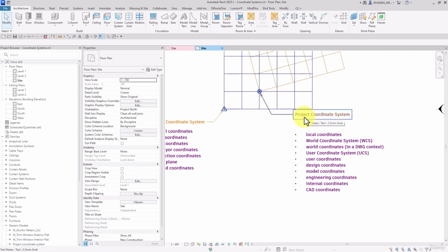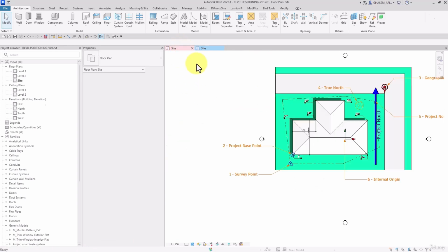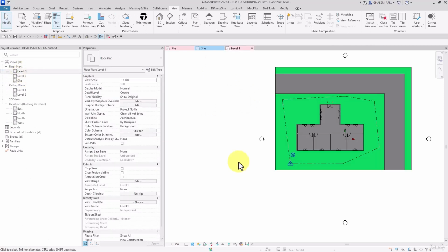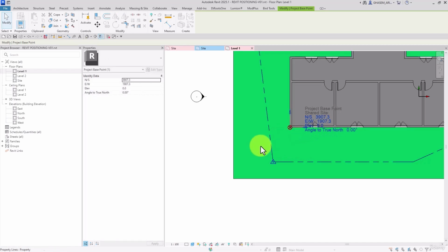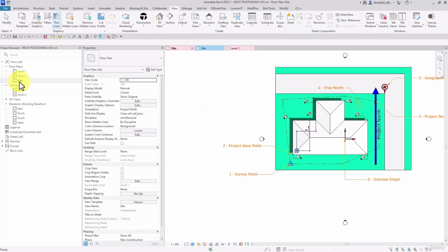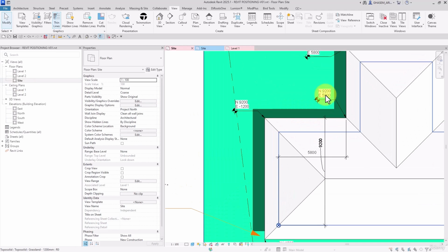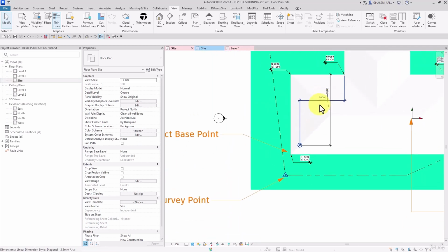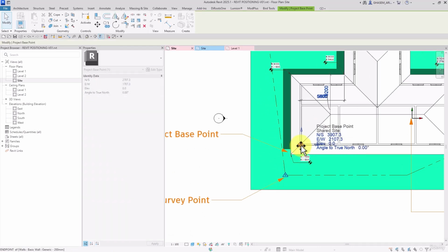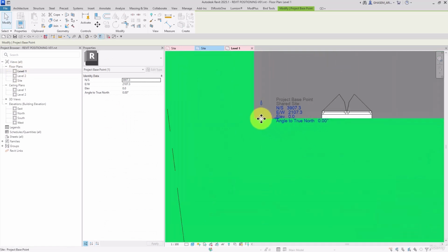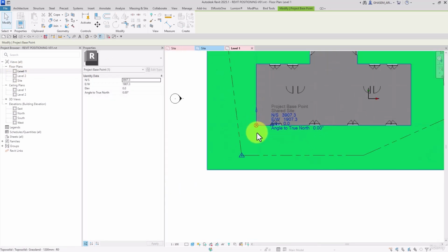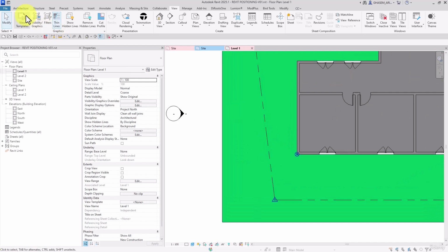And about the project coordinate system, as I mentioned before, this shows the local coordinate that we positioned on the corner of the model, which I can position on the wall or on the roof. Check it out. So right now the project coordinates here are changed. Check it out. The values, height, and width are changed based on the project base point, like this way.